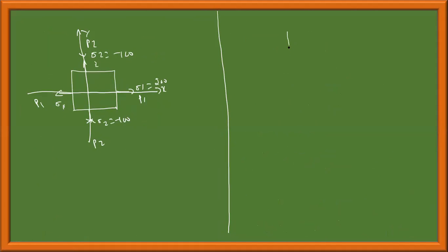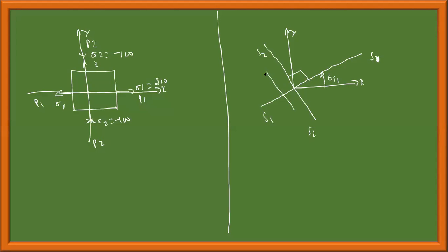To plot the shear stress planes, in the xy plane, theta s1 is at an angle of 45 degrees, counterclockwise is positive, and perpendicular to it, 90 degrees, will be theta s2. The angle between S1 and S2 is 90 degrees. If I draw the plane, I also have to calculate the average stress, sigma average.